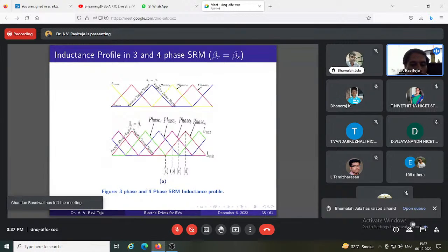It may not take as much time, but if it is taking time, there is sufficient time. I am not asking the winding current to go to zero immediately here. I am switching off beforehand. Still, there is some positive slope region available for me to get the torque, but I am compromising. So if I switch off here, then it has sufficient time.